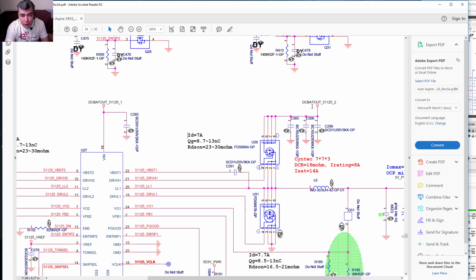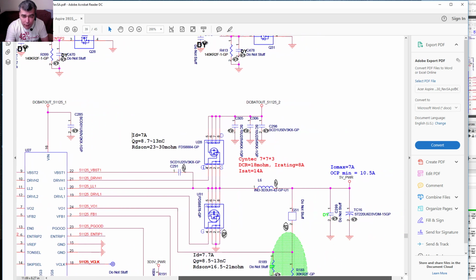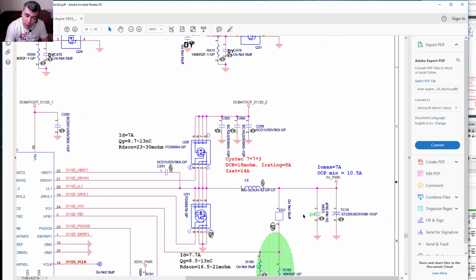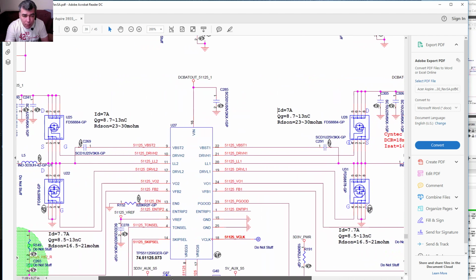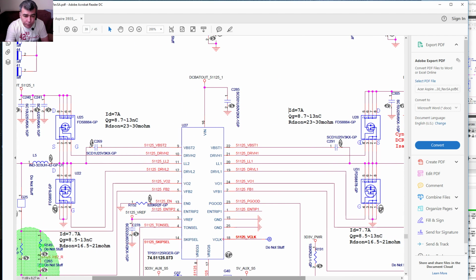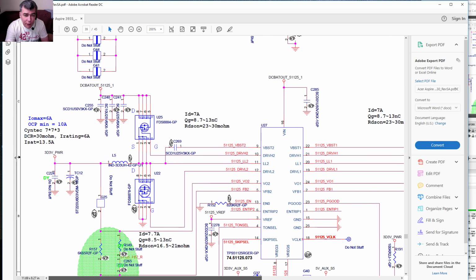VC battery out. Okay, and the electrolytic capacitor after the power supply on the output. This power supply, it's a 5 volts one. Also, these chips are controlled by this big chip, and it can handle 2 power supplies. Here we have the second one, yeah, same, 2 Mosfets, the coil, the ceramic capacitors here, yeah, and the output capacitor.